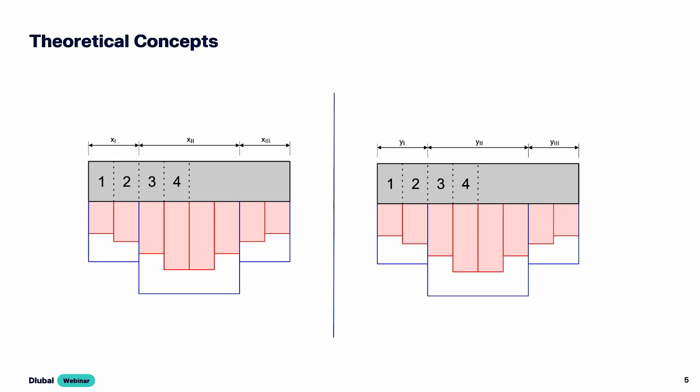The second reinforcement area, x2 and y2, is located in the middle below the column. It covers 50% of the foundation width, perpendicular to the reinforcement direction. The first and third areas are located at the edges, each covering 25%. And these 3 reinforcement areas are the values that are entered in the plate.